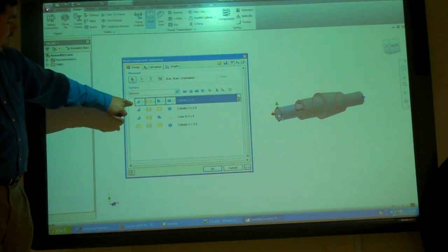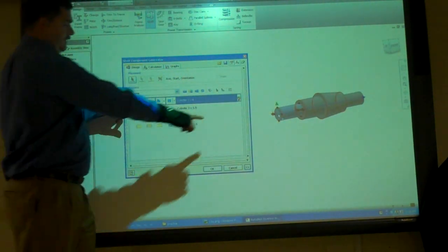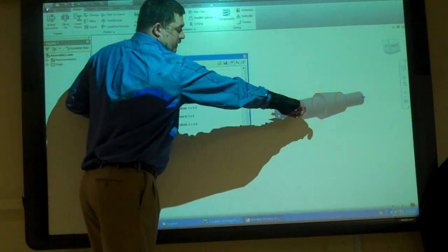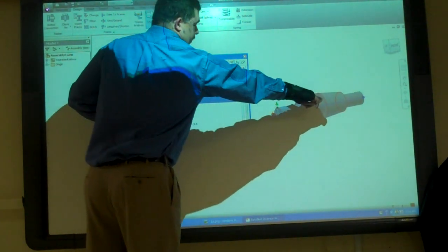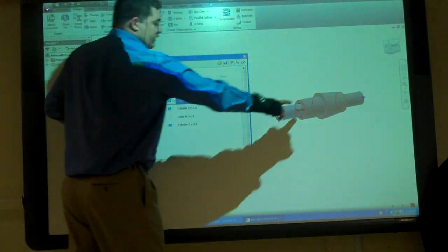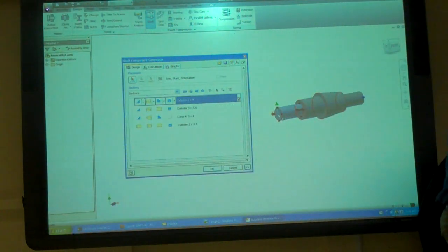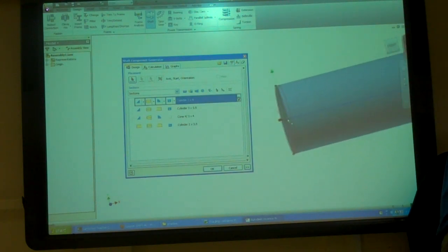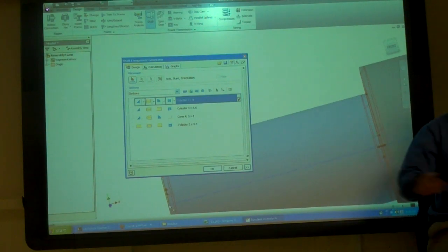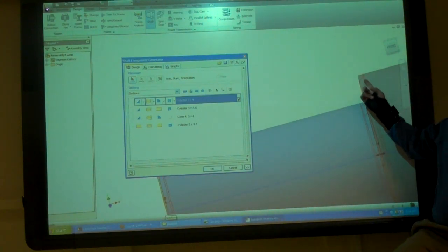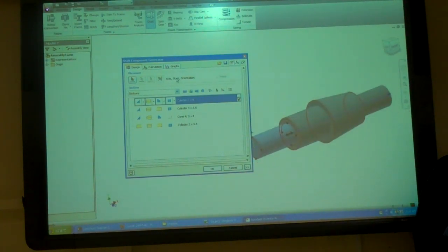Also here I can see that this section has a chamfer on the near side and a fillet on the back side. And this section has a chamfer and a sharp corner, a chamfer and a fillet, and then two sharps. So if I look at that, chamfer over there, fillet here, chamfer there. And so I can kind of define all of that in one box.